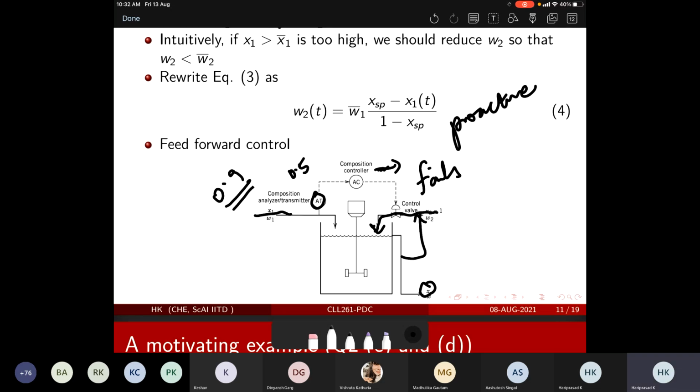So then you did a large corrective action, fine. But after 0.9 for two to three minutes, maybe seconds, it came back to 0.5, which means that this was a wrong reading. But by that time, you have done some large corrective action. Then what would happen? Your whole product is now waste, because you have unnecessarily pumped in the correction, W2, which should have corrected the anomaly, but actually there was no anomaly.